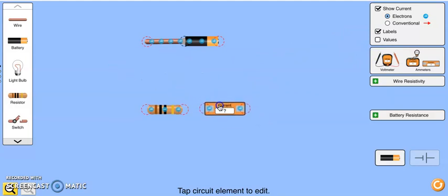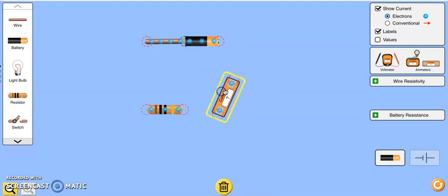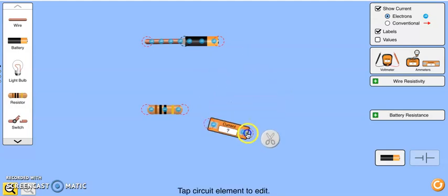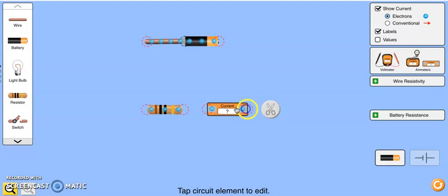So before I make all the connections, I want to put my ammeter somewhere. I can put it here. I can rotate it here. As long as it's part of the circuit, it doesn't matter where it goes. So I'm just going to leave it right here. Okay. So since nothing is going on, even though there's a voltage source, there's no connection, I've got no current. So let's say I were to do this. Okay, so I'm going to connect this to here with a wire. What do we expect the current to be? Okay, so this is already on. There's no switch. All right, make a prediction.